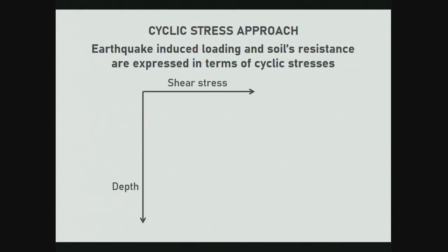Now, there are two things which we need to look at. The first is, what is the soil's available resistance, and what is the load induced by the earthquake. Both these quantities we need to assess in similar terms. And where the soil's potential is less than the load induced by earthquake vibrations, we will say that liquefaction may happen. So we have to now calculate both the quantities.